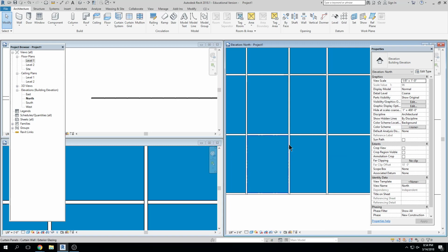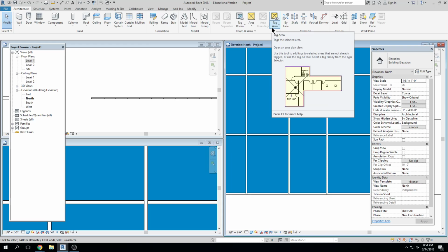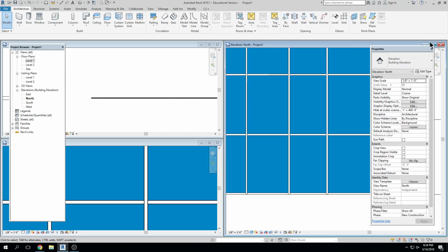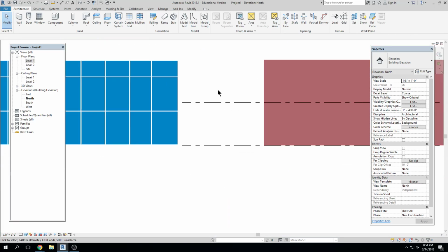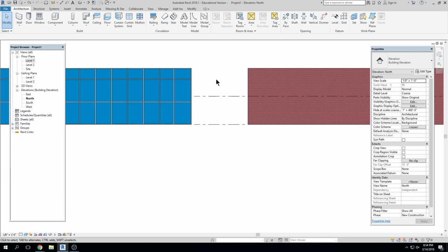Oh. Yeah. It's tricky. You guys are getting the hang of it, but it's really tricky, right? If you haven't kind of gathered that, it's tricky, right? So if you're trying to move it or rotate it or alter it or mirror it or do anything to it, it's really about selection. It's really how you select it as to whether or not it's going to allow you to do something, really. So when I'm placing my curtain or my storefront, and I just stick to storefront, I don't usually put curtain wall in because I don't want to have to define my mullions, right?